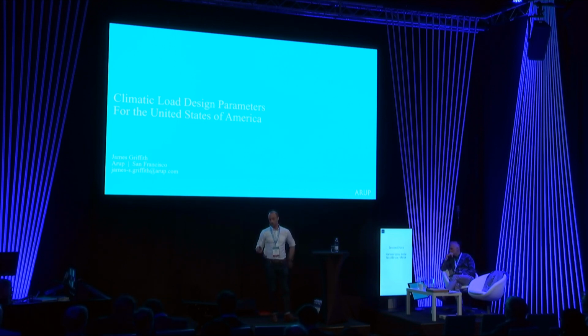Sure. So I guess the scope of this research was really focused on trying to look at those isochoric pressures. In this study, we didn't do much beyond that in terms of the design, applying those, and how to mitigate them. But there are quite a few options out there to mitigate those pressures. As you say, pressure equalization, having breather tubes, and permanent breather systems that breathe through desiccant chambers are all possible. Equally, you mentioned the transportation. There are examples where the glass is transported in a refrigerated unit to try and eliminate those challenges of going over different altitudes.